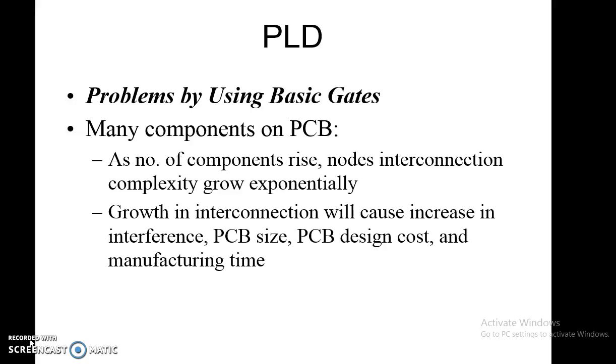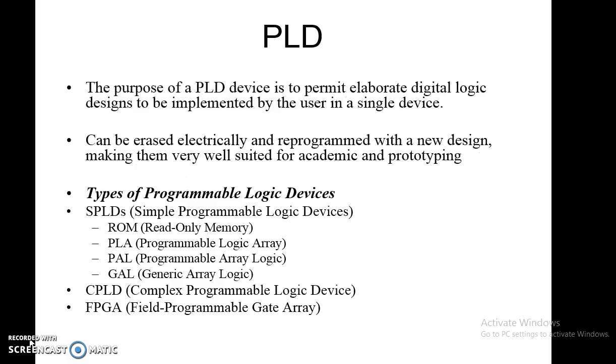PLD, Programmable Logic Devices. Problems by using basic gates. Many components on a PCB. As the number of components rises, node interconnection complexity grows exponentially. Growth in interconnections will cause an increase in interference, PCB size, PCB design cost, and manufacturing times.